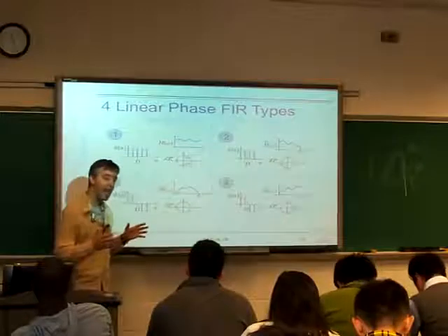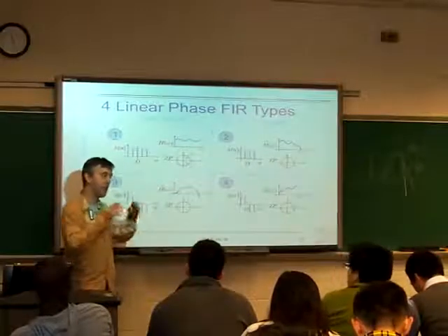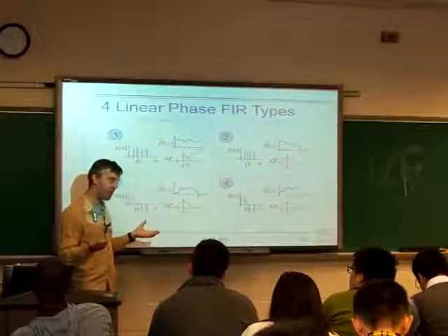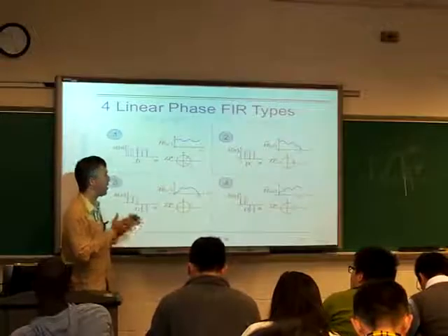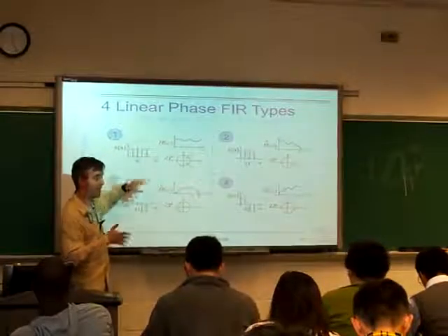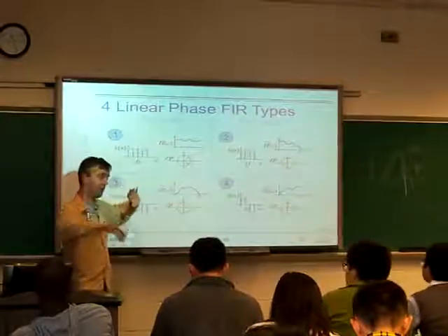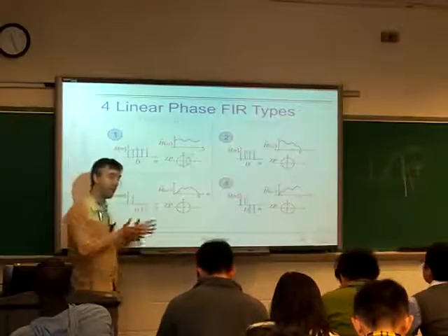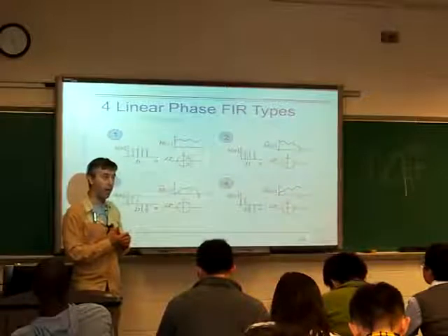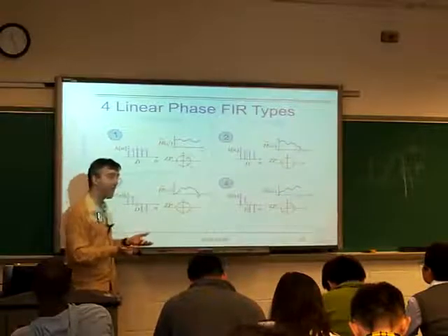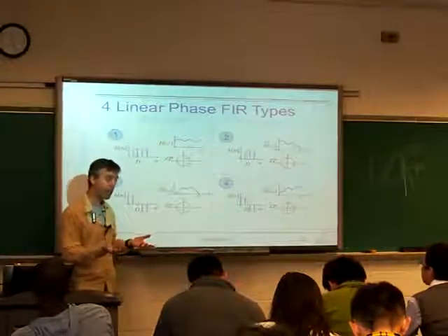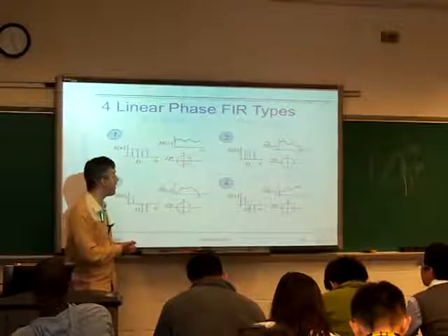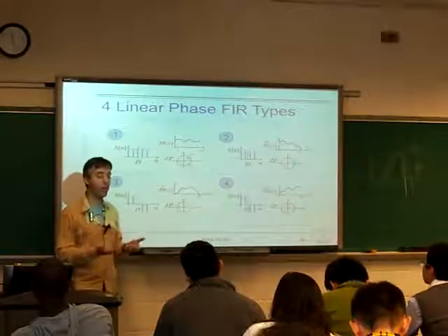We understand how the magnitude responses are built up out of sinusoids, cosines, or sines, up to an order depending on the length of the filter. So as we get longer filters, we get higher order sinusoids to work with, and so we can build more complex shapes. But as we understand from the Fourier transform, from Fourier series, the actual shapes we can build up are otherwise unconstrained.